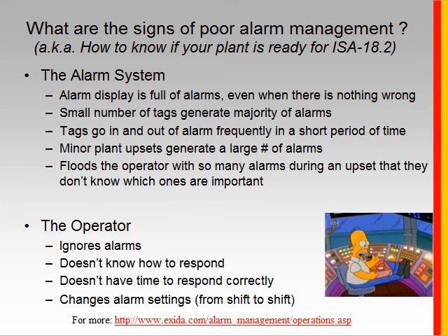You also may find that when you have a minor plant upset, it generates a pretty large amount of alarms that makes it difficult for the operator to understand what to do. In a worst case scenario, in a real significant plant upset, you may flood the operator with so many alarms that he really can't respond and he doesn't know which ones are important.